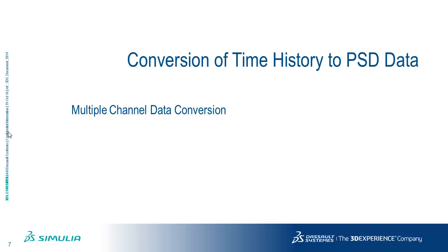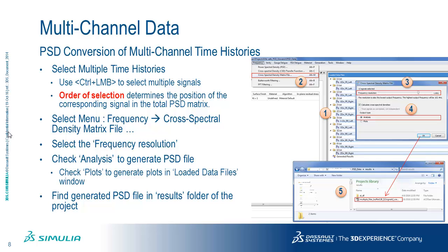And in order to do that, you may need to get the PSD data, right? You can use an external third-party signal processing tool, but we are providing a very nice tool so that if you have a single channel or multiple channel time history, then FE-safe will construct the full matrix of the PSD data.